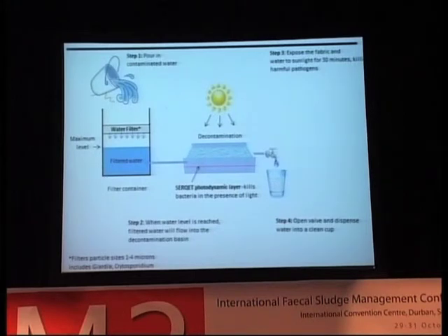It's exposed to light, and the test unit we built in our laboratory was tested by students over weeks and weeks. With our pilot unit we can easily do 20 liters per day in 4 hours of daylight, completely eliminating any cholera bacteria in the water.